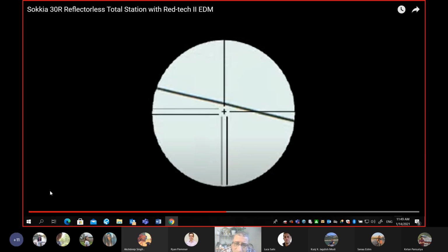Really, it's very handy, and you can see from this video that we can measure points which are inaccessible. Look at the name, inaccessible. Very hard. Look at this. In this picture here, you can see there is a cable, like a power cable, which is impossible to send someone to, or even unsafe to send a prism to this point. And once the point is close to the total station, within a range of 100 meters, I can find XYZ without having to have a prism.